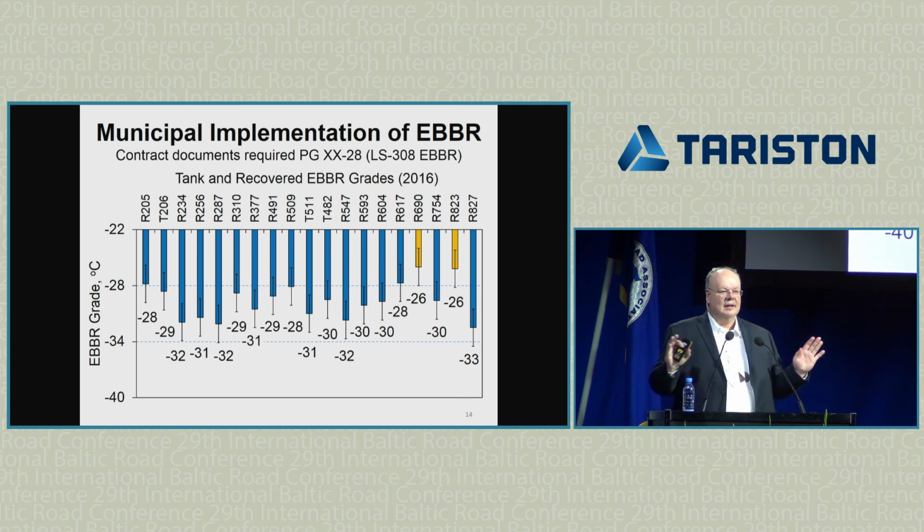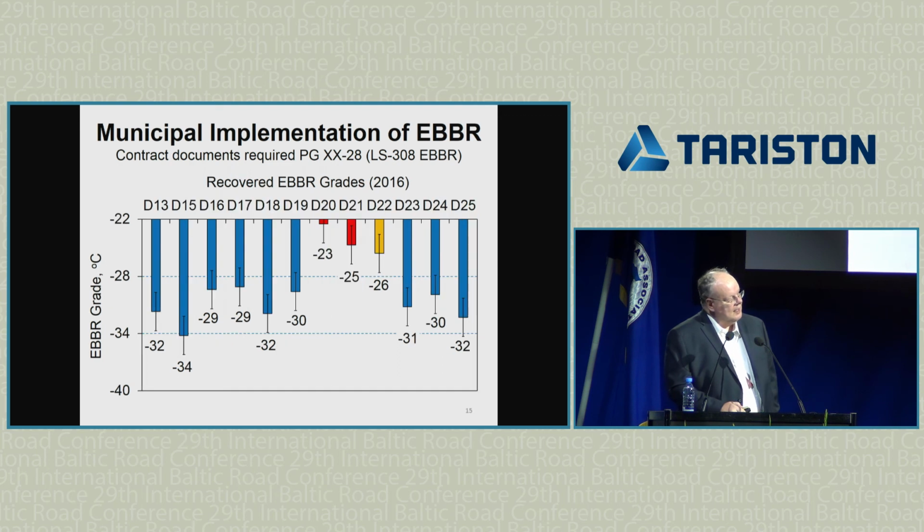They say, okay, we can't come in, health and safety. Please come back another time. We give you a can of asphalt, this is what we're using. But they may well be adding RAP when no one is looking. This is another municipality, and we have 3 samples that are no longer minor borderline. Well, one is, the other 2 are failures. What should be a minus 28 is a minus 25, that's a big problem. Or a minus 23, that's a disaster.